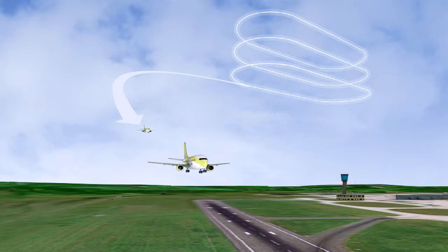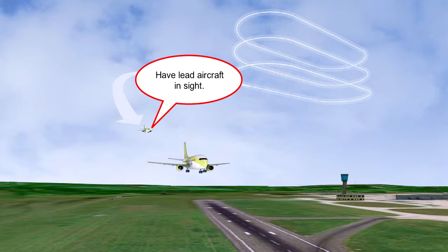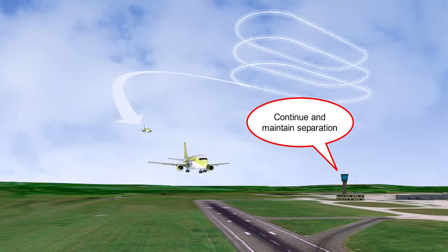Aircraft separation shall be provided between all aircraft cleared to execute a visual approach, and all arriving and departing aircraft. For successive visual approaches, radar or non-radar separation shall be maintained until the pilot of a succeeding aircraft reports having the preceding aircraft in sight.